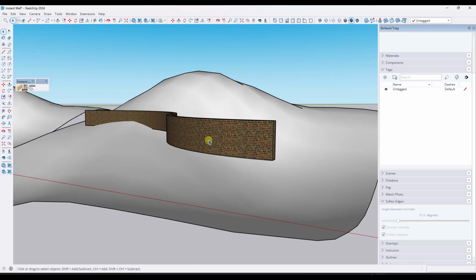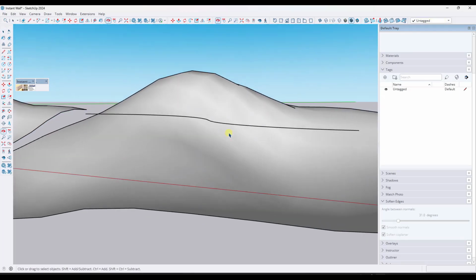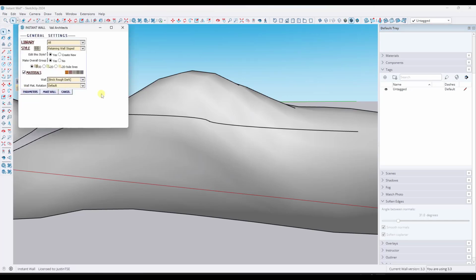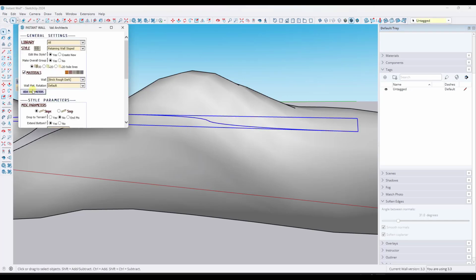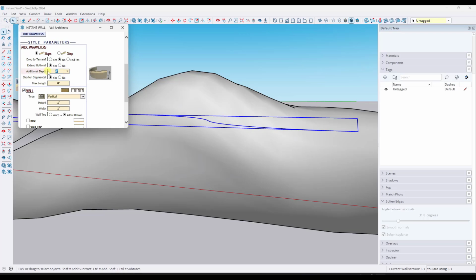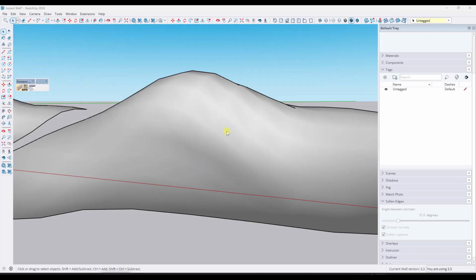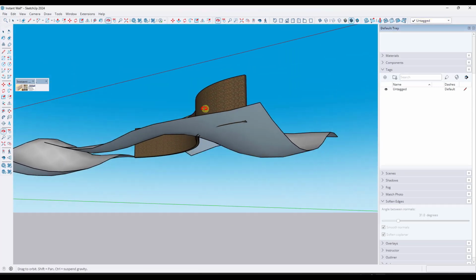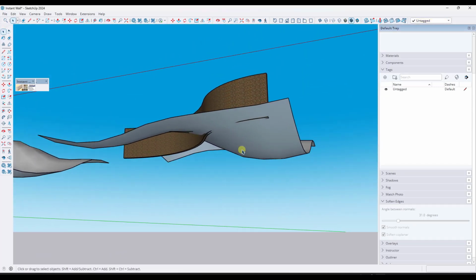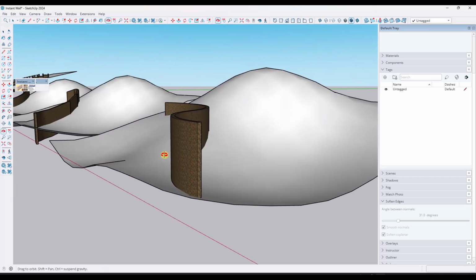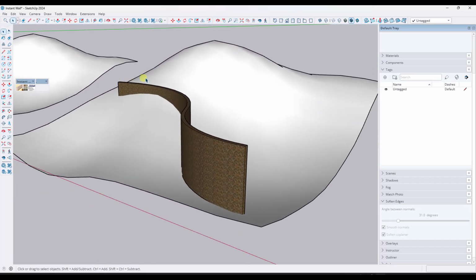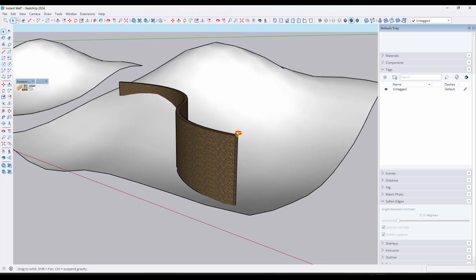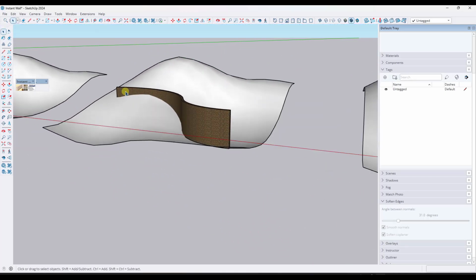So in a situation like this one, if you've got a huge thing that you're filling in over here, then what you might end up doing is adding a big additional depth in here. So you might call it like 14 feet, make a wall. And so then it's going to add that additional depth in here, and you can just use it in order to extrude through this surface right here.